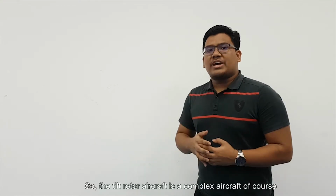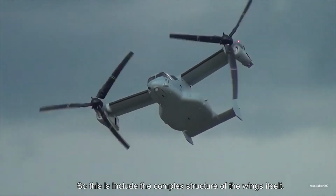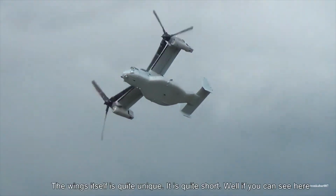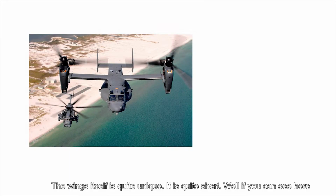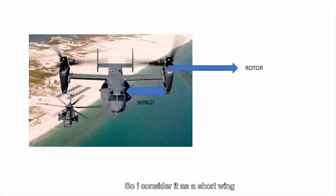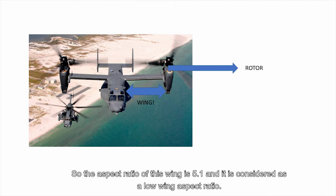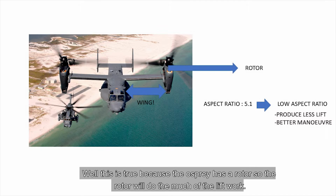So the tilt-rotor aircraft is a complex aircraft, of course. This includes the complex structure of the wing itself. The wing itself is quite unique. It is quite short. Well, if you can see here, the wing is long, but at the end of the wing is the rotor. So I consider it a short wing. So the aspect ratio of this wing is 5.1, and it is considered a low wing aspect ratio. A low wing aspect ratio means that it generates less lift and can maneuver much better than the high wing aspect ratio. Well, this is true because the Osprey has a rotor, so the rotor will do much of the